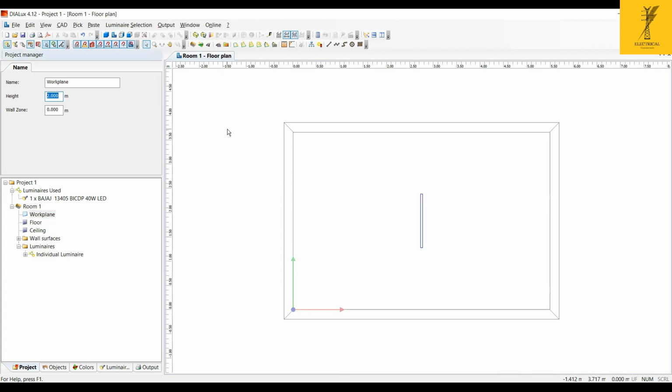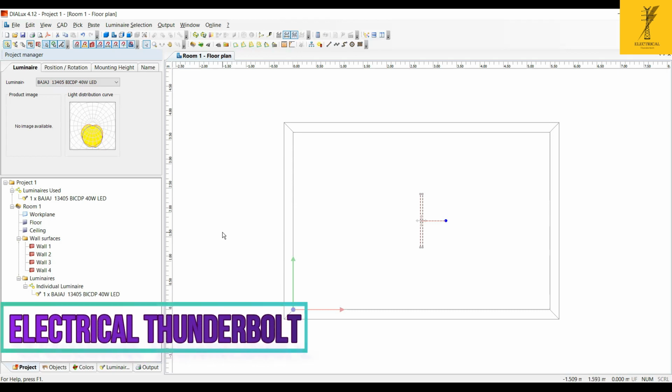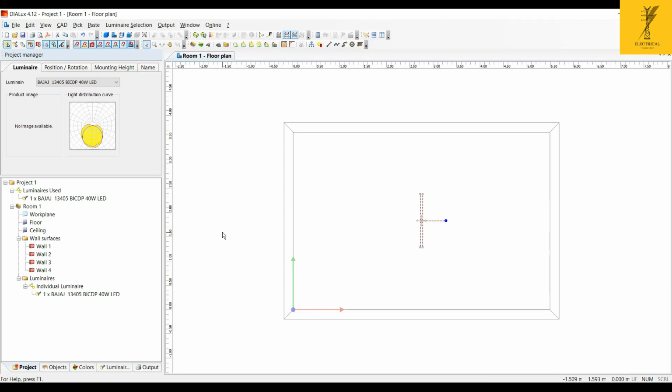Normally, the required values shall be checked at that level, not at ground level. For example, in a control room, sometimes there are 400 lux at a work plane, or desk plane. Yes. For office rooms, generally we see 400 lux at desk level, where we are writing notes or working, right? So we are checking at the desk level. Suppose I am doing the same illumination in some cable rooms, there I have to check up to ground level, where I can see so many cables. So depending upon the activity, the work plane changes. Got my points?